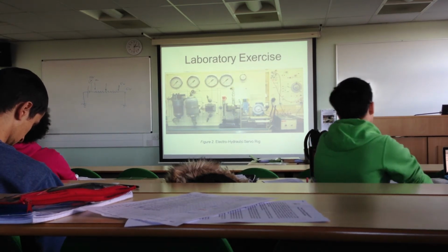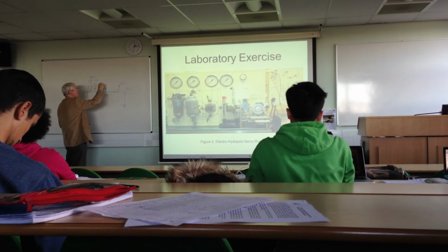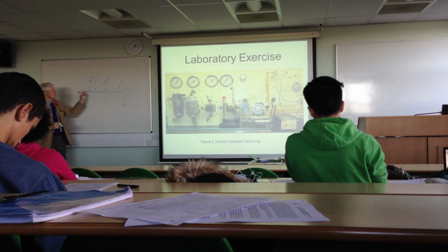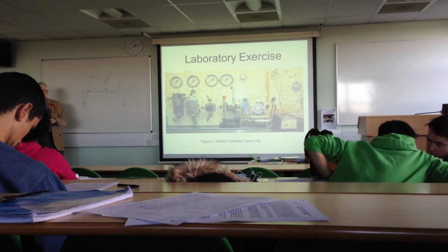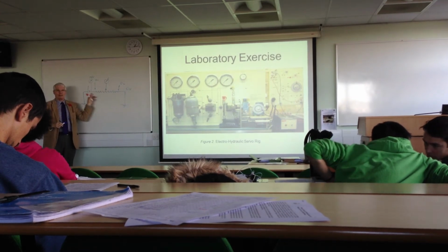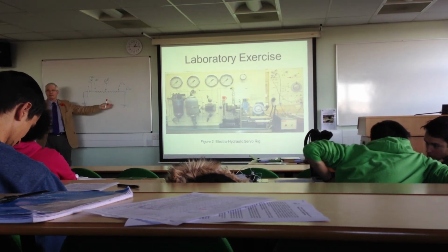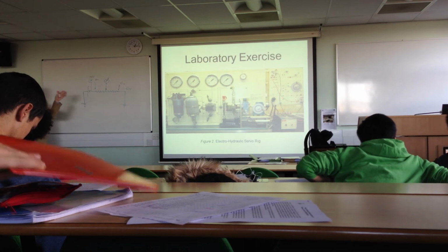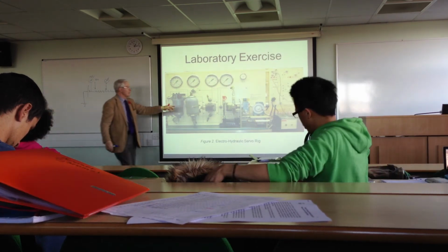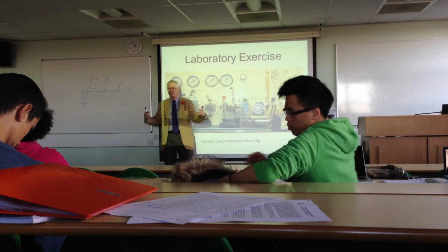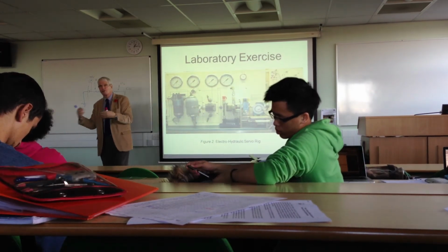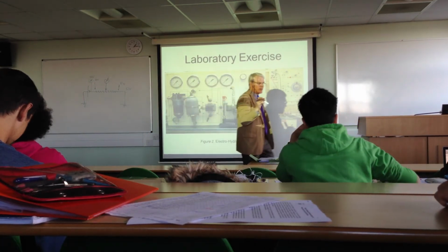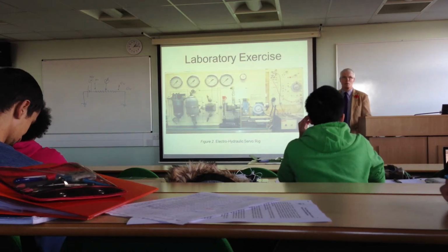So basically, if that was our linear transducer, the voltage that we would read on here would be proportional to where we move. The only thing is, when you've got a sliding contact, you're wearing away the electrical coil. So they don't generally like contact transducers. What we've got in here is usually a magnet going into an induction coil, and you get the same thing, a voltage coming out proportional to where it is. So most transducers are non-contact, so they don't mechanically wear out.